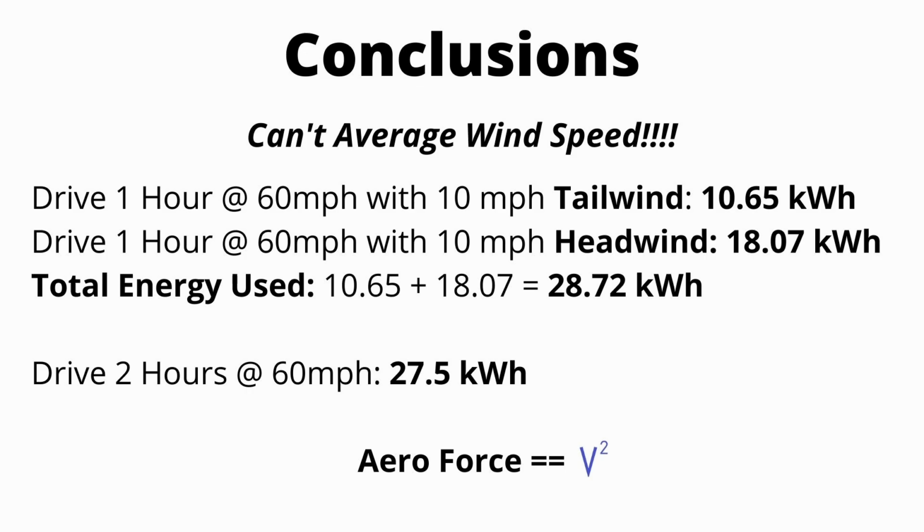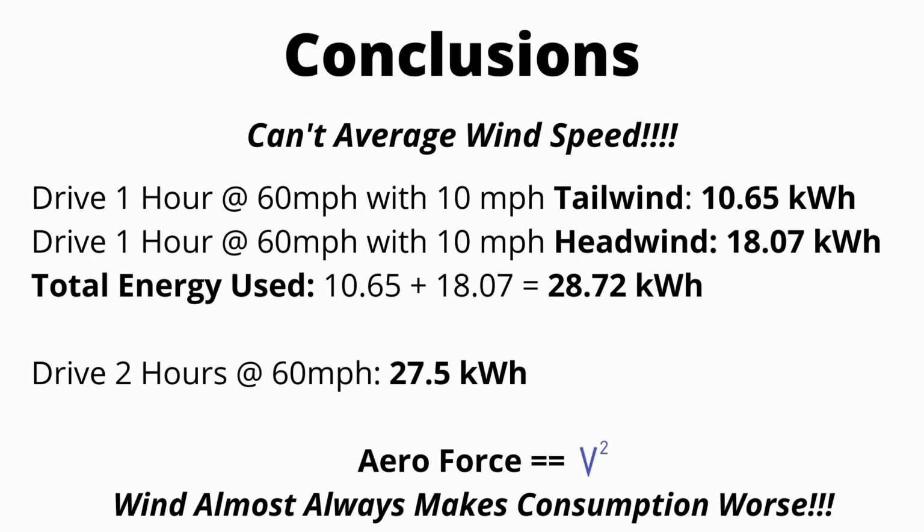And so my whole point here is because the aero force that acts on the car is correlated to the velocity squared, you can never average wind speed. So if you're going to do some sort of round trip in a car and it's really windy, you can assume that you're going to get far worse range in general, even if you're doing a perfect round trip and the wind doesn't shift, than if there was no wind at all. So the whole conclusion I'm trying to get across is wind almost always makes consumption worse unless you're driving with a really consistent tailwind.